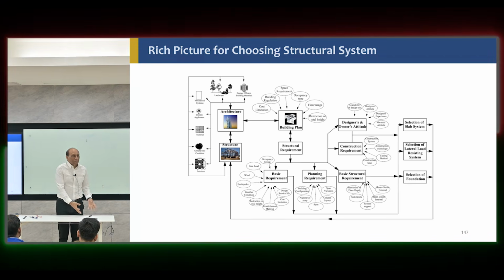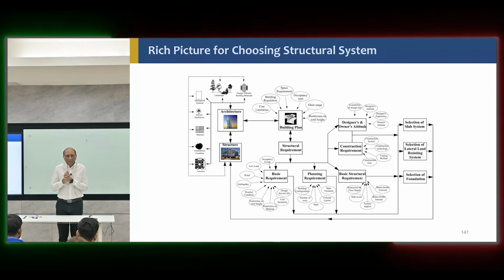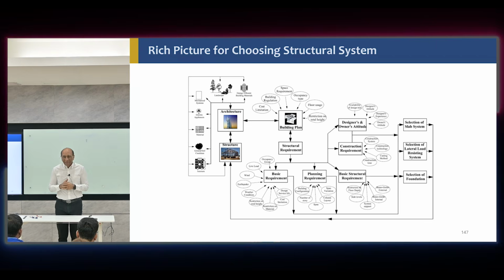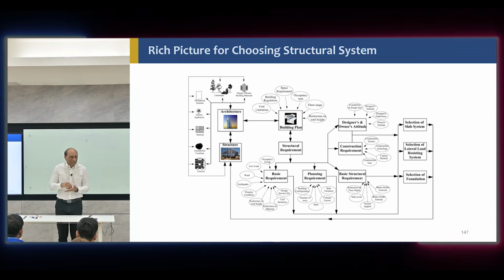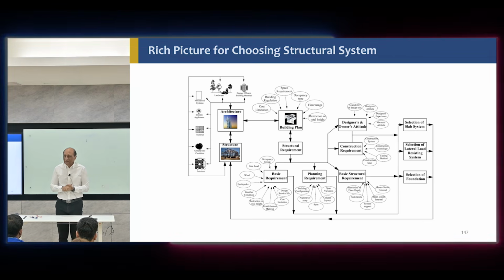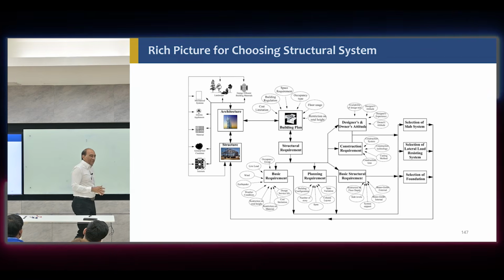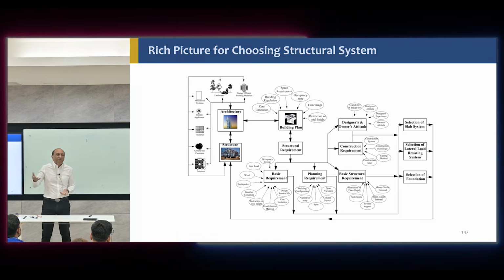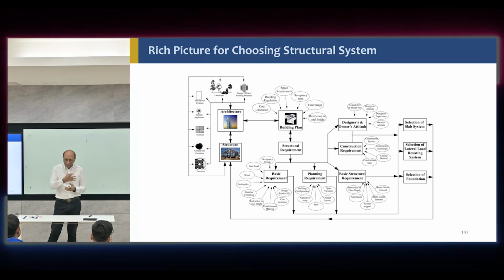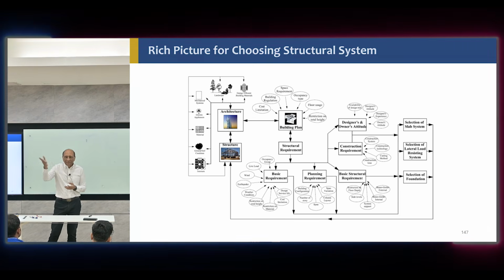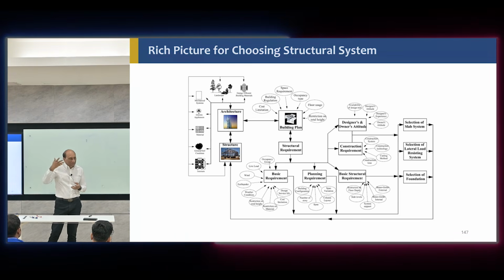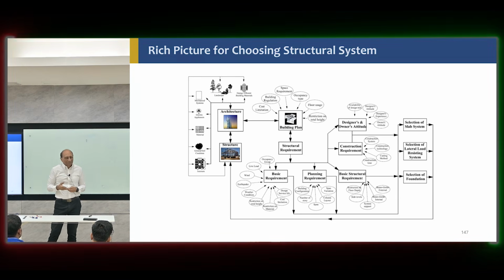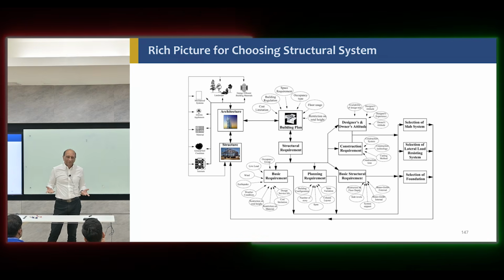And I said, okay, I want to use flat slab here. He said, no, you cannot. I said, why not? He said, because we don't know how to design flat slab. We only know how to design beam slab because we don't have any computers, anything. Flat slab is very complicated to design, so we don't design it. So just because the engineers did not have the experience to design flat slab, they never designed any building with flat slab, even though that was a better system for that project, because for a hospital, they needed a lot of flexibility in the air conditioning and the other systems below the slab, and beams were obstructing all that ducting. But they didn't want to do that because the engineers didn't have the experience.